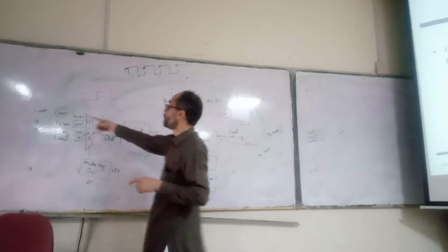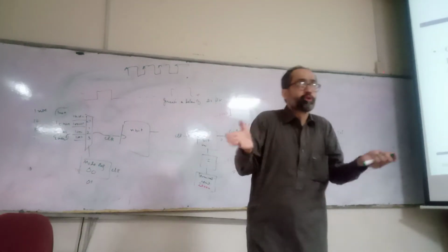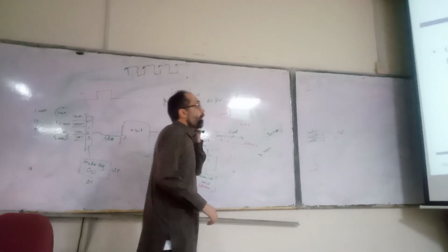It depends on the user requirement, whether you want good resolution. If you want good resolution, you will go for a faster clock. If you want to increase the range, and resolution is not a problem, you will go for a slower clock.